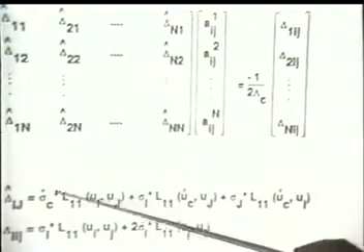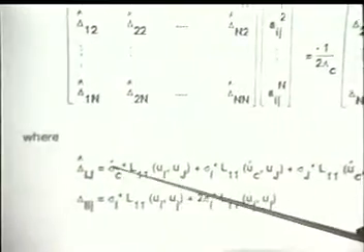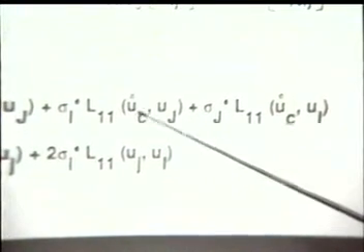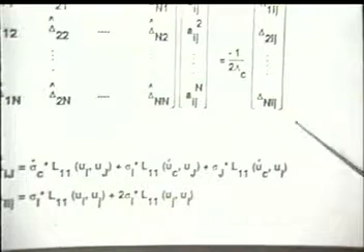There's something else that appears here. You have here a sigma c. That is the stress resultant of the buckling mode evaluated at the bifurcation point, and you have a dot. Now that is d/d lambda, derivative with respect to the buckling load. Remember, we do a Taylor expansion around the bifurcation point. There is once again a dot here also. Notice also that, for instance, these terms here, what is that? That is a buckling mode evaluated at the bifurcation point. If I'm using membrane pre-buckling, then this is 0 and this is 0, so these terms disappear. If you use rigorous pre-buckling, they exist.